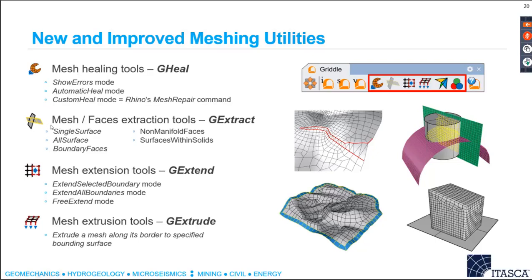Another tool that we have is the mesh extraction tool. It received many more sub-options. Previously, it had only single surface extraction. Now we can extract all surfaces, which is somewhat equivalent to exploding meshes. We can extract boundary faces, non-manifold faces, and surfaces within solids, like shown here.